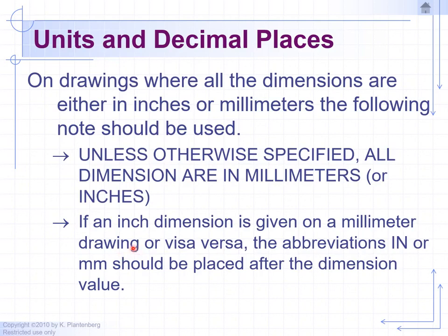Now it's very rare, but once in a while you will mix millimeters with inches. So on our previous slide, we were dealing with inches. So all the dimensions are in inches because it told us in the title block that all dimensions are in inches. It's very rare, but once in a while you will create a drawing where you have all the same units. For example, all are inches. All the dimensions are in inches, but there's this one hole with a special size diameter, and the part that inserts in that hole, that part only came in millimeters.